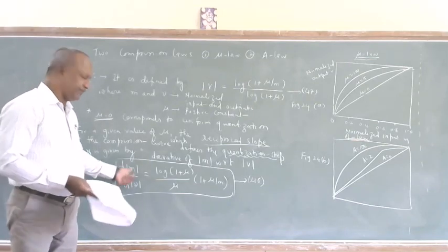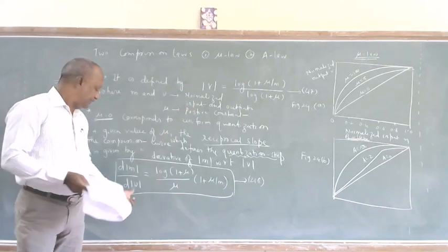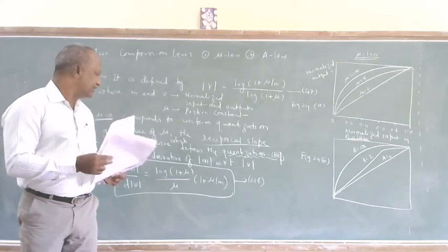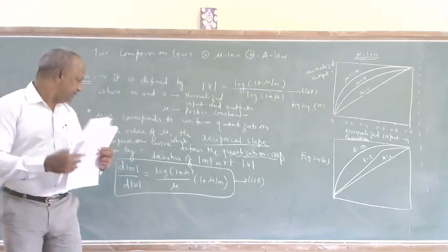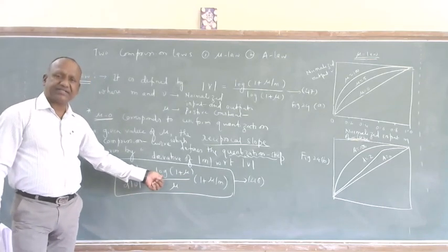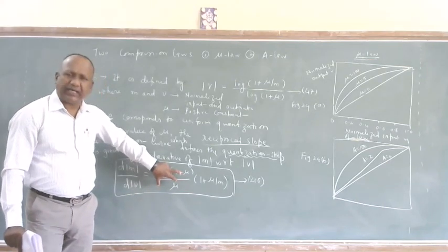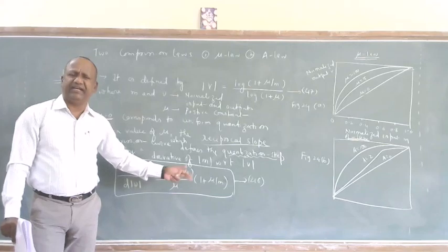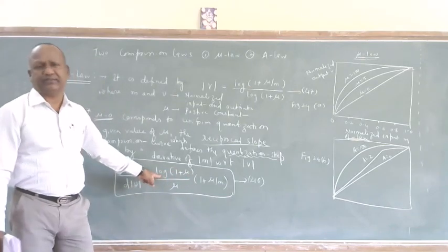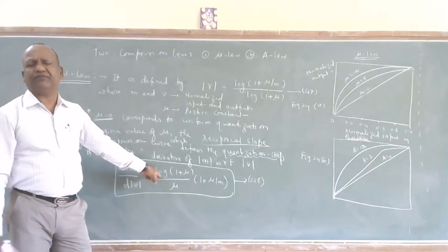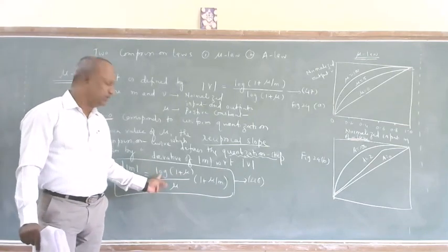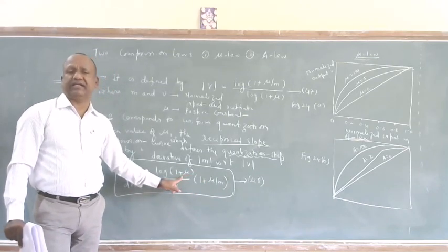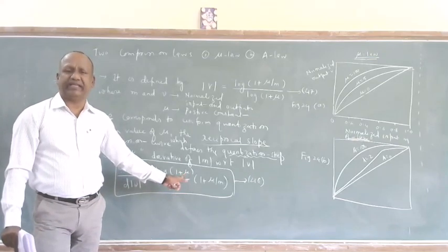Okay, so the differentiation of this equation with respect to the given parameter, finally you get this answer, which is giving you a quantization step size. Now this quantization step size looks like it is neither linear nor perfectly logarithmic. Is it linear? No, because there is a log term. Is it perfectly logarithmic? No, because it also has some other constants here. So it is neither strictly linear nor strictly logarithmic.